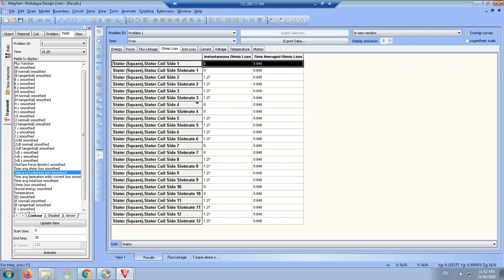Well, it depends. You have to look at the permanent magnets. If there's no conductivity associated with the permanent magnet, which means there would be no eddy current losses in it. Oh, maybe. So it's possible they're not showing any because there's no conductivity. It's possible MotorSolve set the permanent magnet conductivity to 0. So yeah, you're probably right. It should be there, but if it's zero conductivity, there won't be any losses, so it's not showing them. You're right. I think that's what's happening.